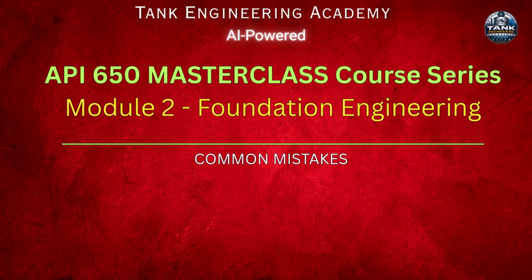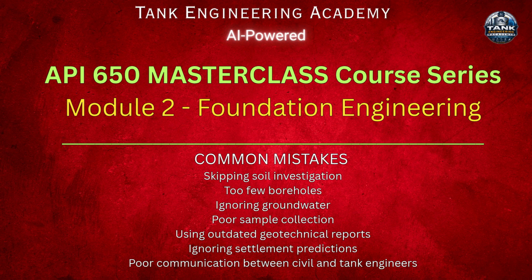Common mistakes. Avoid these common mistakes: skipping soil investigation, too few boreholes, ignoring groundwater, poor sample collection, using outdated geotechnical reports, ignoring settlement predictions, poor communication between civil and tank engineers.